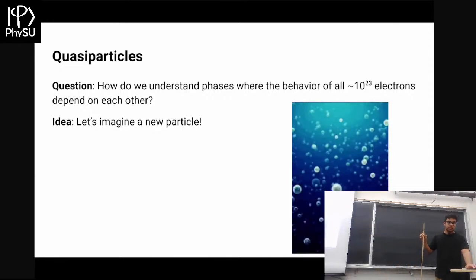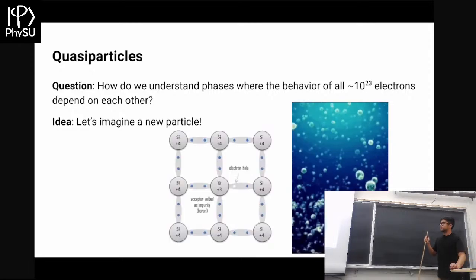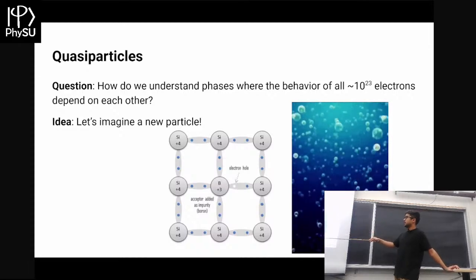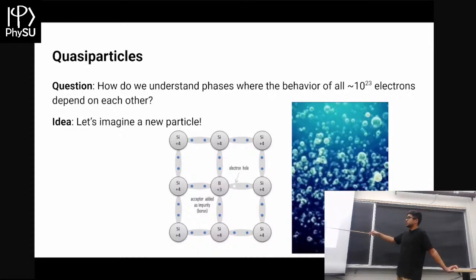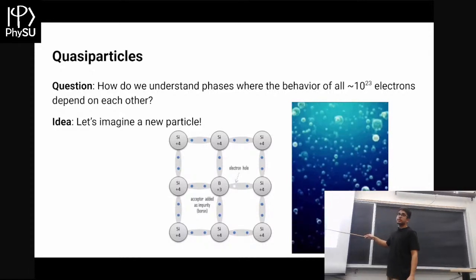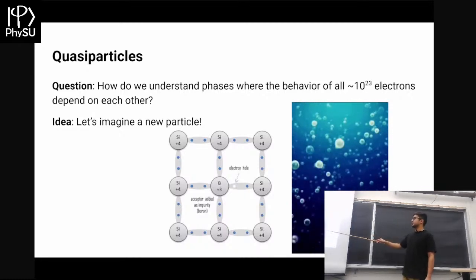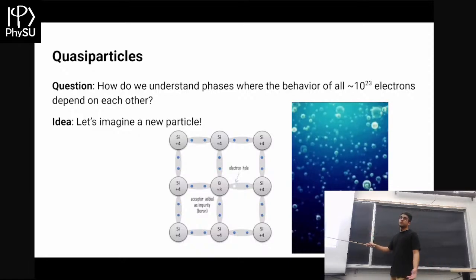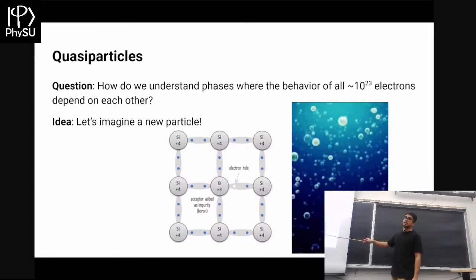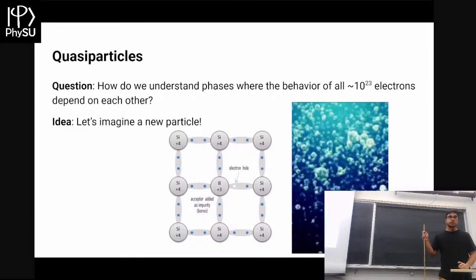So in a solid state system, what this looks like is this. Imagine we had silicon atoms in a lattice, each of them sharing two electrons between them. Now imagine there's one impurity, boron. It has one less valence electron, so there's an electron missing here in this bond. Now, the option is we have all these electrons here and we can imagine them moving around, or we hold the electrons in place and imagine just this vacancy of an electron moving around. That's what we call an electron hole, and that's used a lot in solid-state physics, especially for understanding semiconductors.